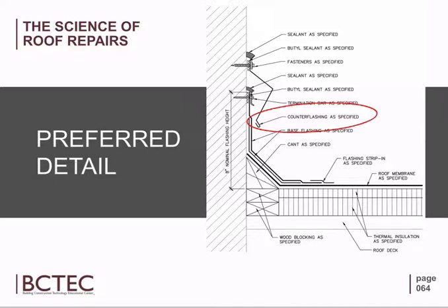Well, what I would do is, for one, make sure all your fasteners are snugged up. You saw in the previous photo that the fastener is actually backed out. That was probably due to original install. They stripped that brick out with the screw fastener. So to make that repair, snug up those fasteners, replace what's necessary, add more sealant, but then come in with the counter flashing system, just to cover that termination bar and get any exposure of the UV rays off the top of that roofing system. And that counter flashing will help you do that.